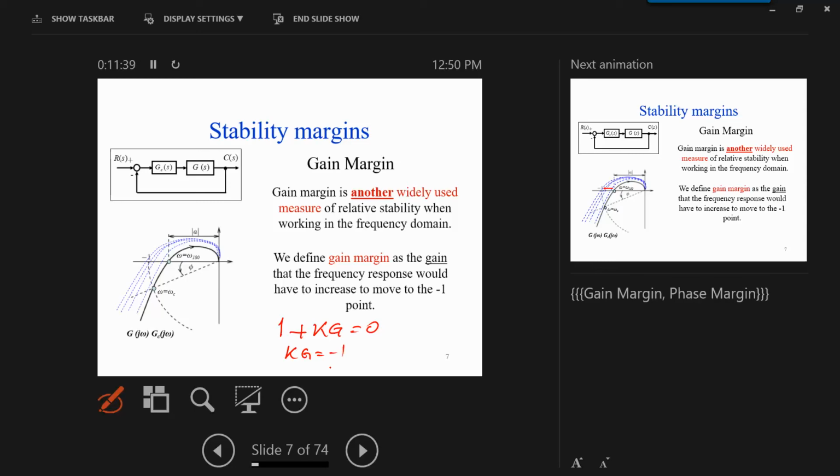This is the circle of -1 radius. And this is the -1 radius, this is the crossover frequency, omega c, okay? So this is the specification. I want you to focus on the Bode plots, okay? The Nyquist plot is a very useful plot, but we can obtain Nyquist also from Bode. This is not extra information, it is the same information, but how you are presenting the information.